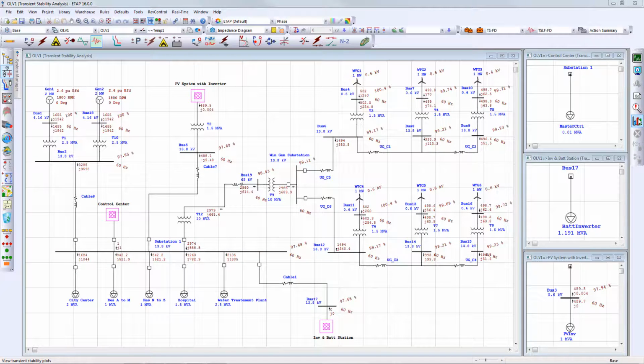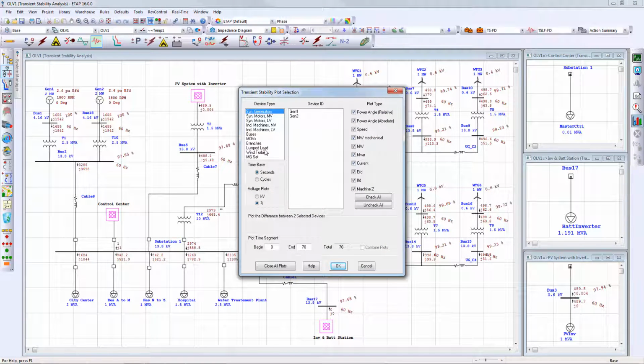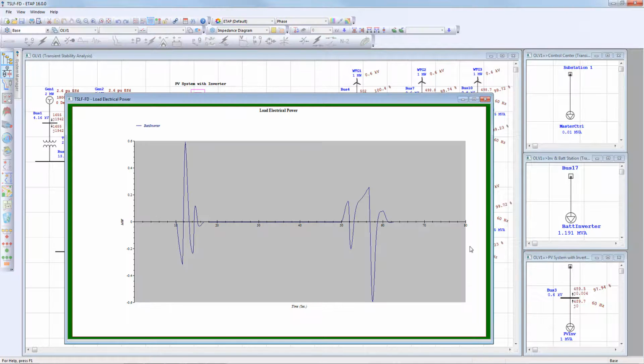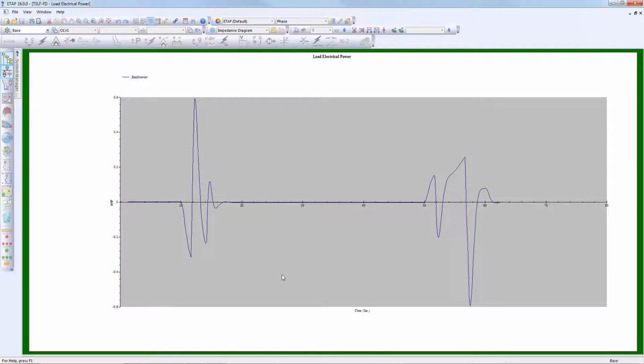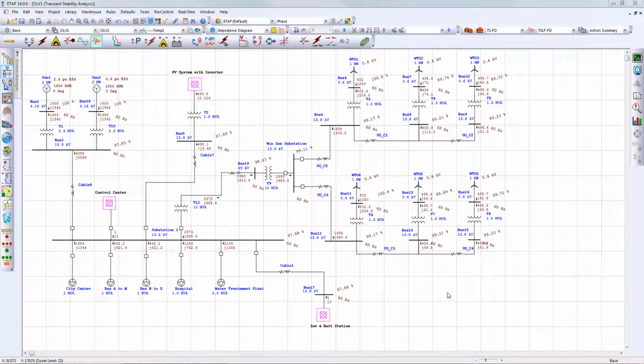Our final graph in this section will represent the energy storage device, which shows that it either charges or discharges active power into the system as the frequency changes. This element will then improve the frequency performance of the systems during transient wind generation conditions. Our next example will now focus on how the new tools in ETAP 16 UDM can be applied to wind turbine simulations.